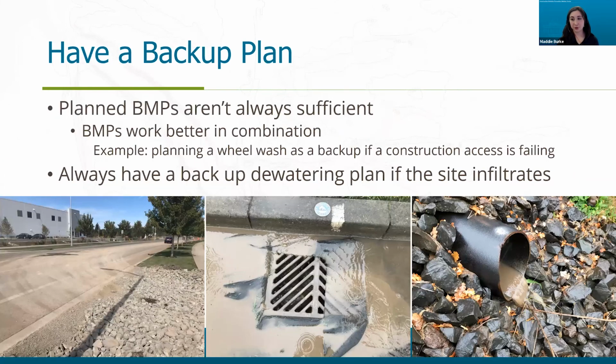So Jordan talked about this, the contingency, but you have to have a backup plan. Planned BMPs aren't always sufficient. So you can definitely in your SWP include an initial BMP and then have a backup BMP in case the first one is not working out. And BMPs always work better in combination. So it's great to combine a wheel wash with a construction access.